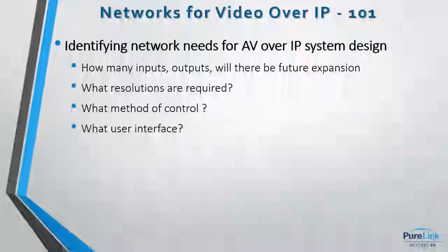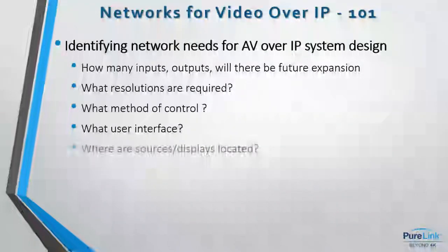What kind of interface? So again, common. Do you want remote control, handheld infrared remote control to control the system? We're one of the only companies that offers that. Or do you want RS-232 going to a Crestron system with a touch panel, or QSYS or Savant or AMX or Extron? What control for? Who's your interface? The good news is all our stuff has a rich API. We can work with any of them.